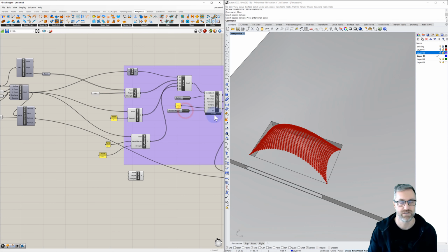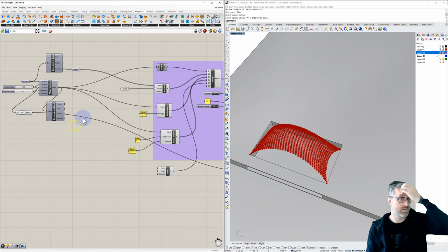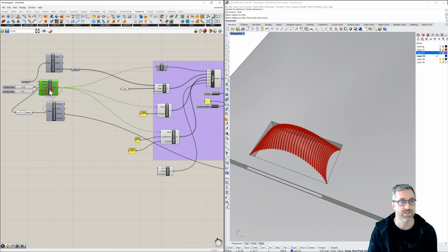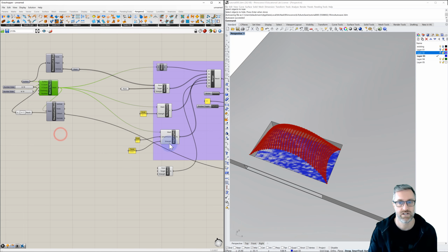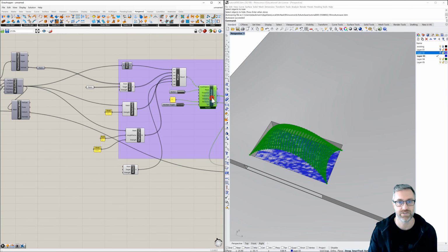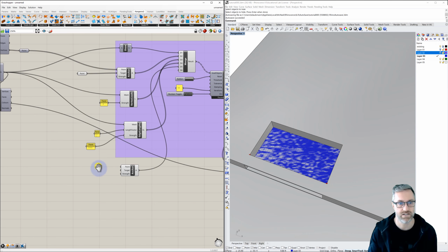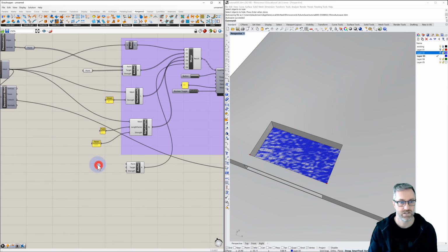I'm just going to pause my solver for a minute while I do this. And let's plug in our anchor to our merge. So we have it. Now let's do what we did earlier. We will bake our mesh surface just temporarily. I can hide my bouncy solver. And let's set some points. We'll make a point container. We'll plug this into the point.